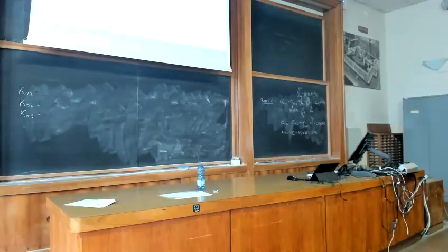If you look at your stratigraphy and your input data, you can see that your soils are not over consolidated. Why? Because there is no OCR in the list of parameters. Otherwise, you should have this parameter in order to define K naught.